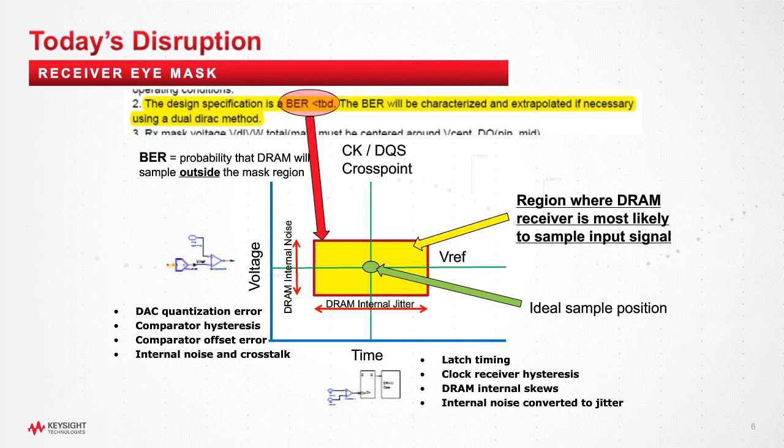Well, I think we all know, of course, that there's actually a data valid window. There's a metastable region for each flip-flop. And so that means that that point isn't exactly fixed in time, but usually it's a very small amount compared to the overall timing of the system. When you start having to deal with things like random noise and random jitter, however, what you find is that that relatively fixed point starts to move around.